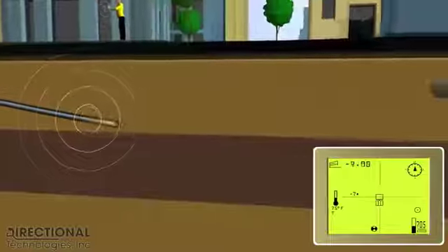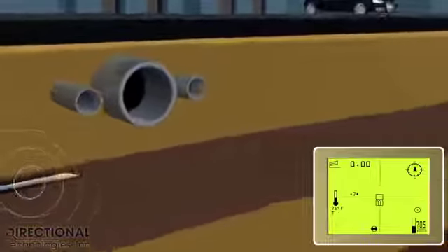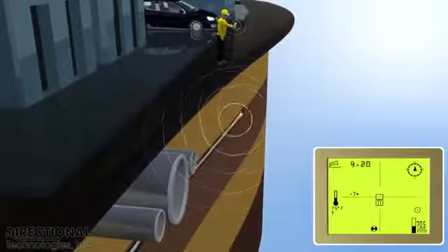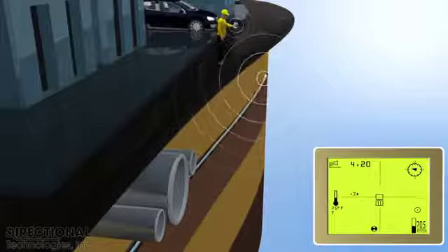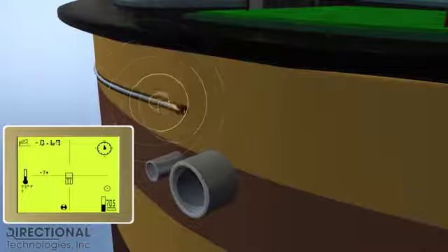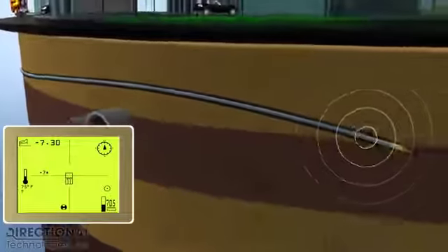The directional drill bit is tracked by a sonde, our radio detection device, housed within its extended connection to the directional drill pipe. The depth and pitch is sent to the surface and received by the walkover locating device. The locator then gathers and interprets the information and gives directions to the directional drill operator on which way to